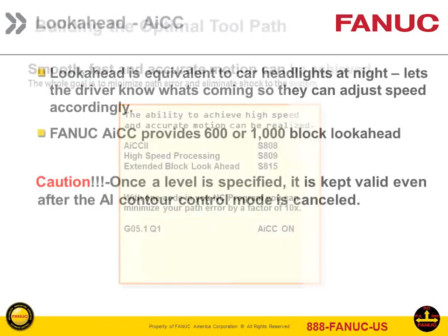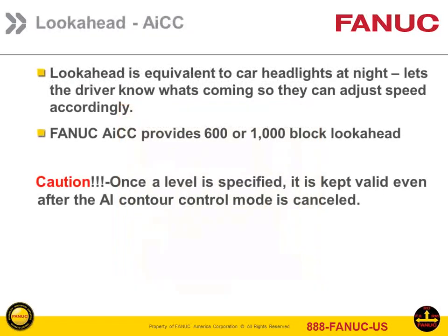Okay. And then, talking about look ahead, FANUC loves to use the driver analogy. Look ahead is equivalent to having car headlights turned on, so the driver can see ahead what's coming up, so he can allow for it. That's what look ahead will do. And with FANUC, you can get up to 1,000 block look ahead.